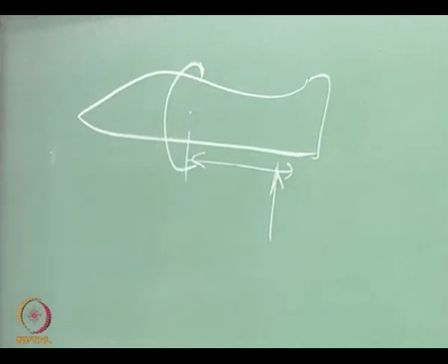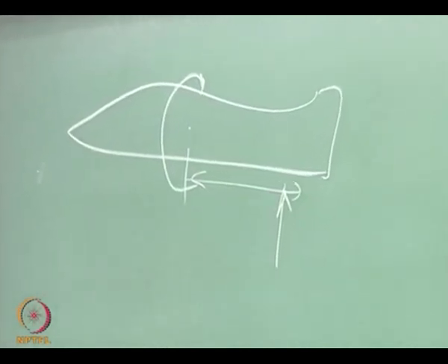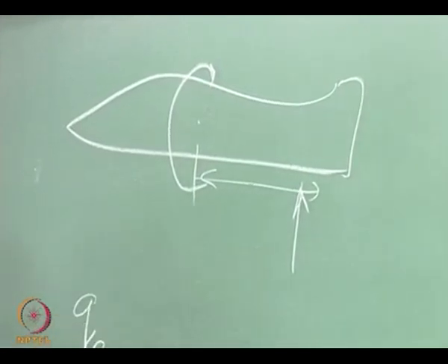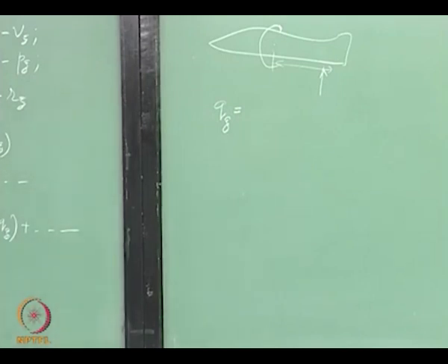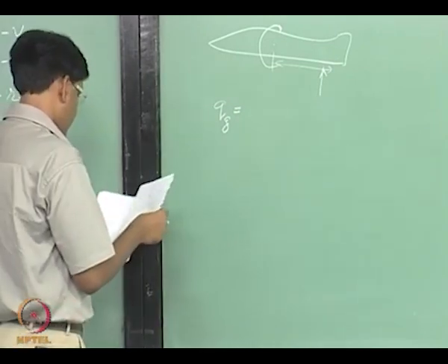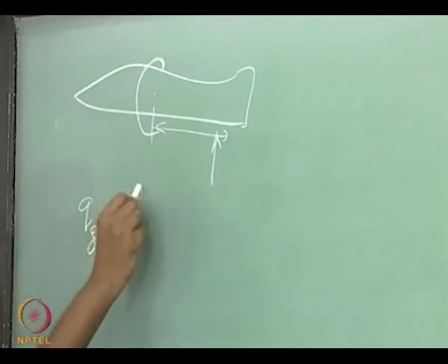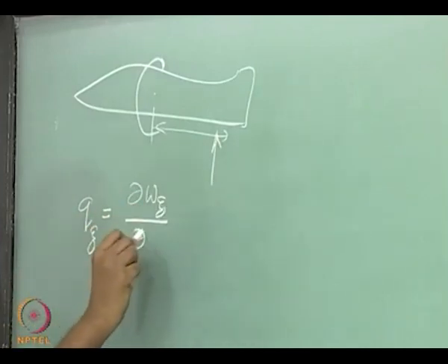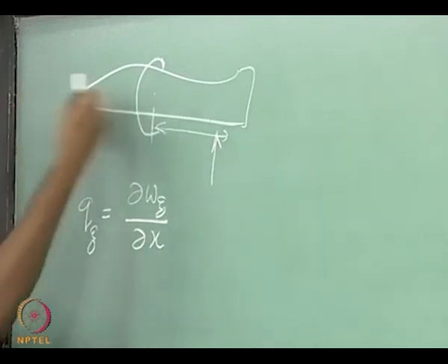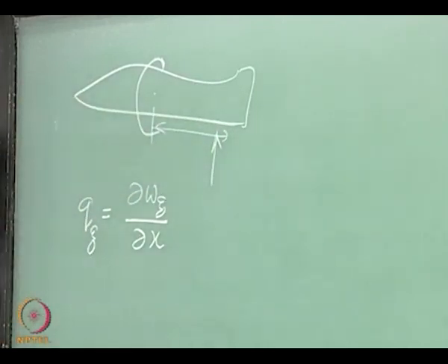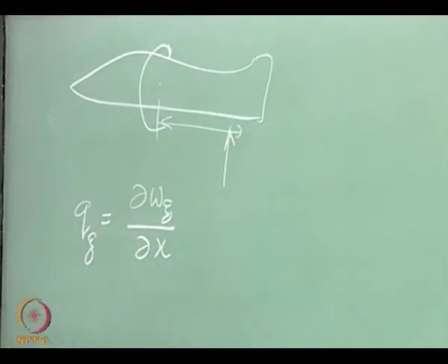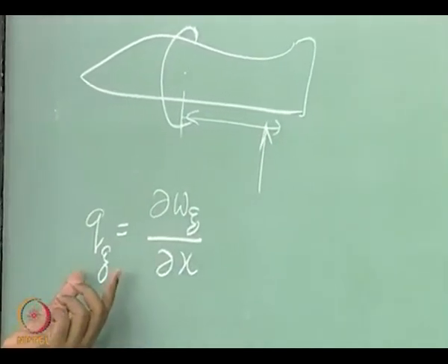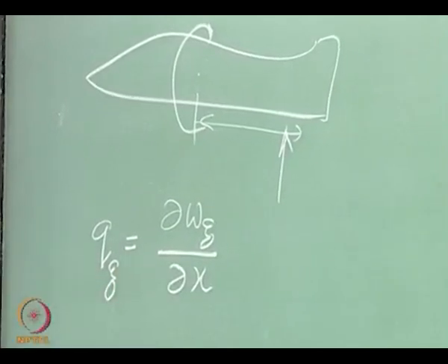So, going by the same argument, you can write this QZ as, right. This is the x direction. If you have wind changing along the x direction of the aircraft, then it can give rise to this pitch rate, which is rotary gust, right.